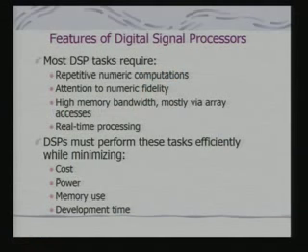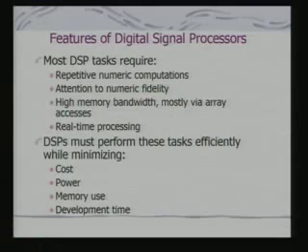Power consumption also becomes important, because I won't like to do any kind of processing consuming a lot of power, because the majority of my embedded appliances would work on battery. And for memory usage, there is also a restriction. The restriction comes from the constraints of power as well as that of the size.